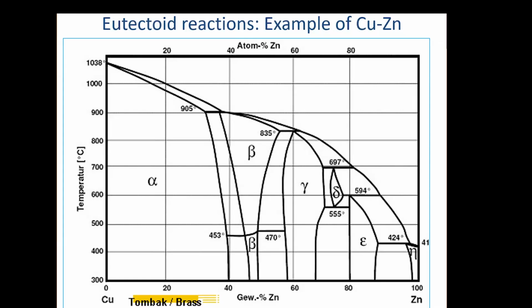Is it the delta phase? Yeah, delta. See this delta phase? This is a little solid solution, little delta phase. And it has a little minimum here, right? There's a little gull wing shape. Your eye should start being able to pick these out, these little gull wing shapes. And so this is a reaction. You cool down the high temperature phase of the delta solid solution, and when you cool through that point, you go into a two-phase region.